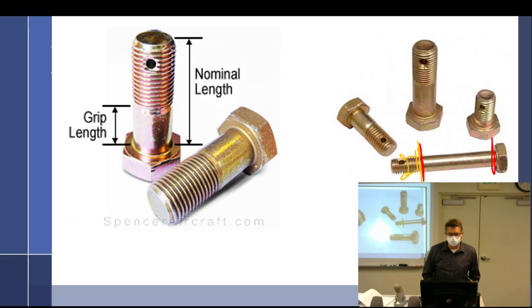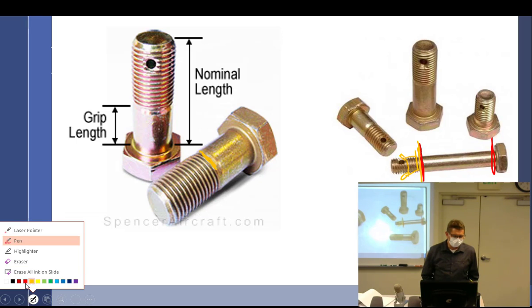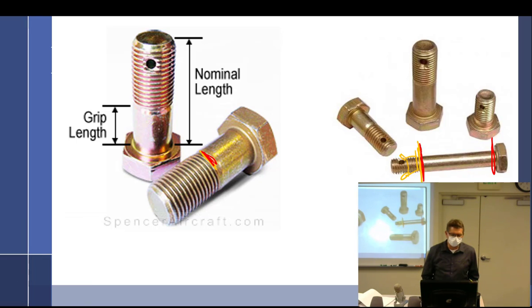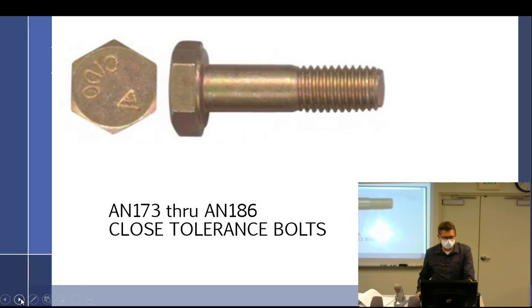Why? Because all the stress is mostly concentrated right here in this first thread. It's just a matter of the way the bolt is. So you don't want what you're bolting together and all the stress to be met at this exact same spot, where you could have some shearing action going on. Most of the time it's just engineered where you don't have to worry about it. These bolts aren't necessarily being used to their final yield torque, if you will.